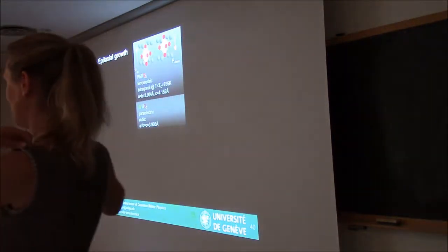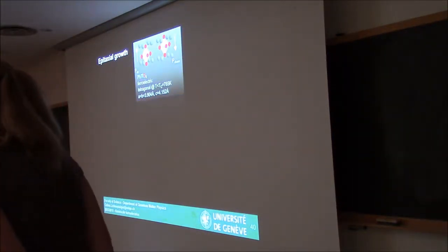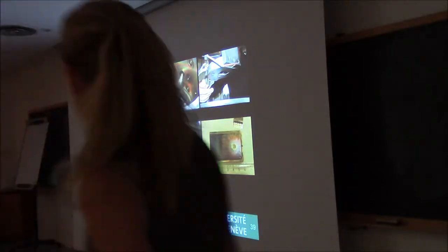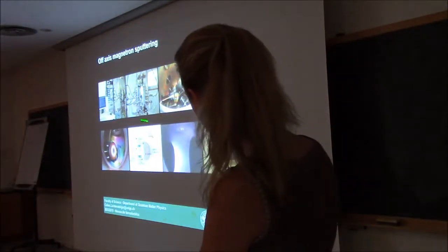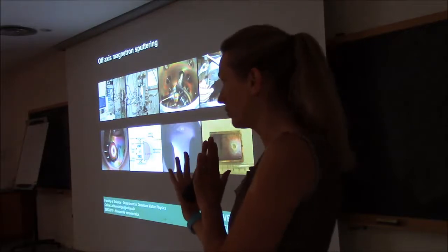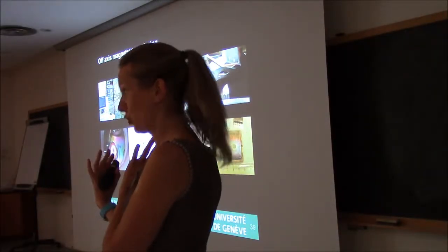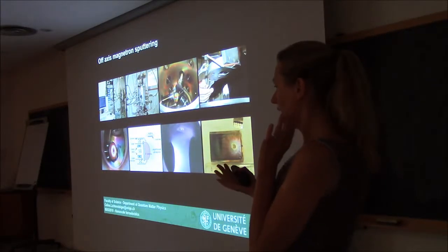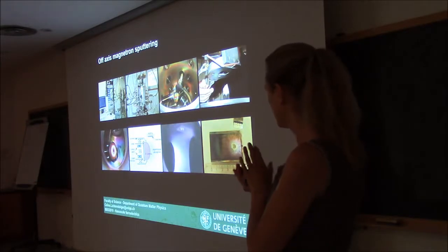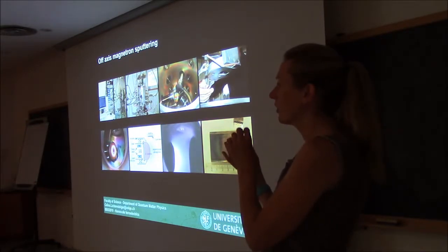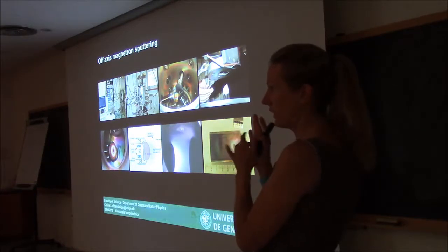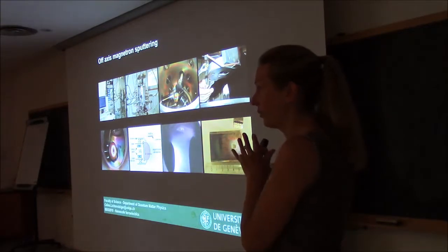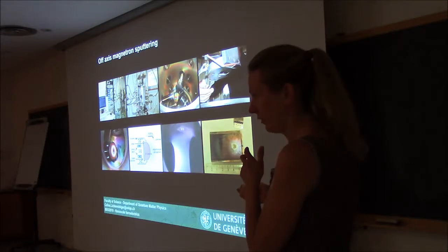I have a question about the sputtering. I'm not very familiar with it, but why do you want to do it at such an off angle instead of... This is because of stoichiometry. We do this off axis, with the substrate here rather than in front. The process is much slower when you do that, but the energy of the atoms that come to the surface is lower, so when they arrive they will not remove those that were already there. So it's much more gentle for the sample.